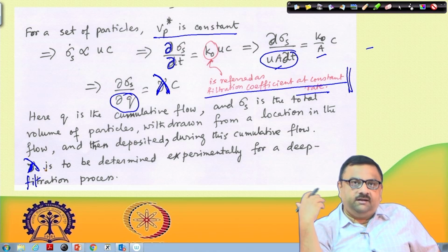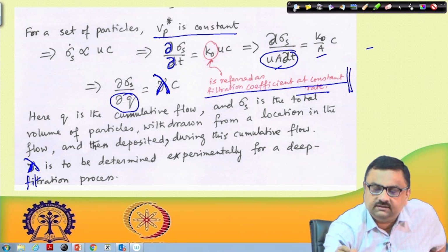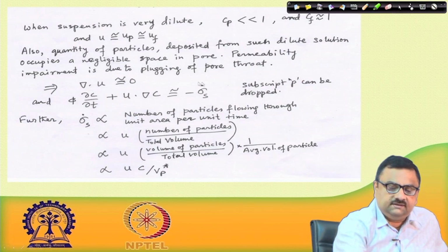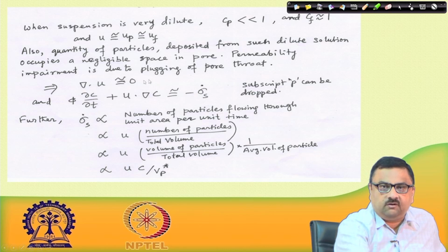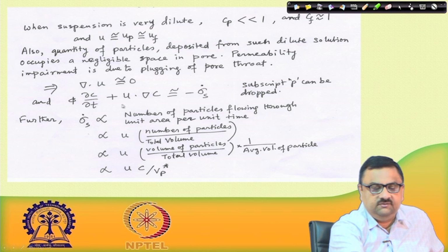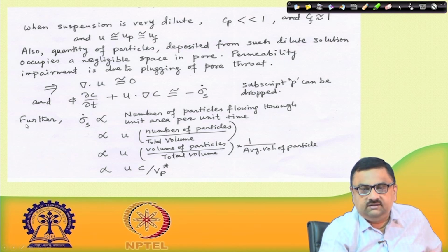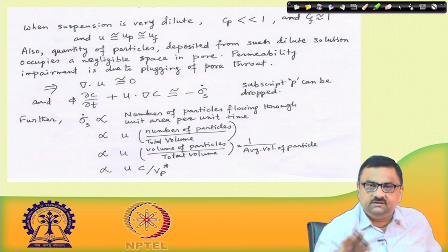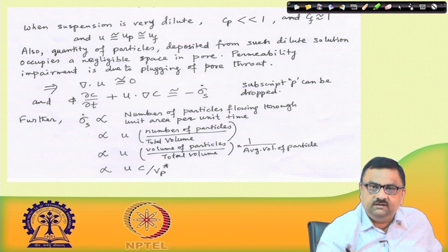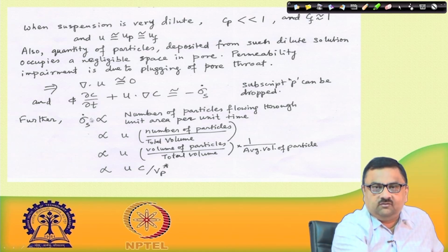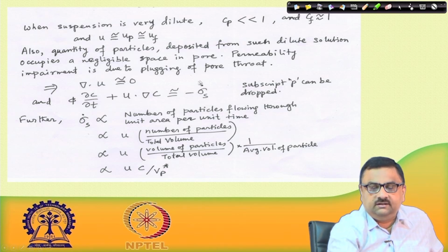So, where are we all heading to? We said that this is the simplest form of bookkeeping we have with the particles. I pick up a differential volume, particle is going in, u is outside, phi is outside. So, only whatever is going in based on the velocity I have from outside, no change in velocity, nothing. So, it is within the differential element. In minus out is the accumulation in the fluid phase and the deposition on the solid surface. The most simple bookkeeping we have here.